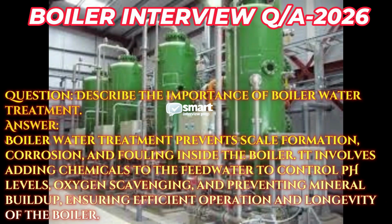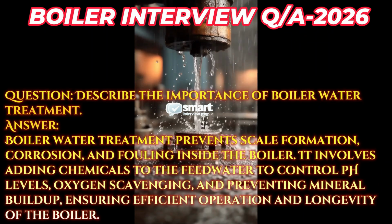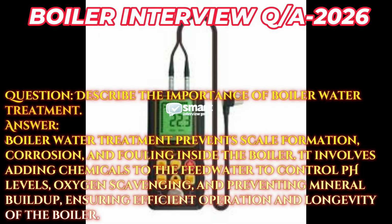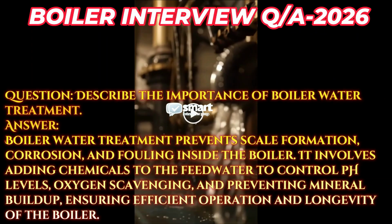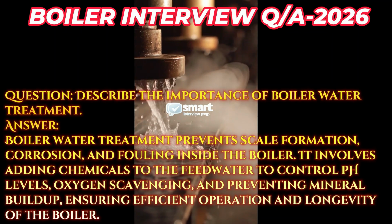Question: describe the importance of boiler water treatment. Answer: boiler water treatment prevents scale formation, corrosion, and fouling inside the boiler. It involves adding chemicals to the feedwater to control pH levels, oxygen scavenging, and preventing mineral buildup, ensuring efficient operation and longevity of the boiler.